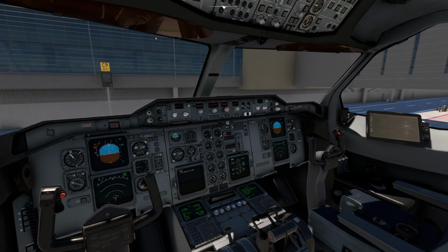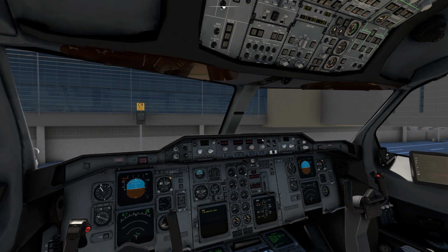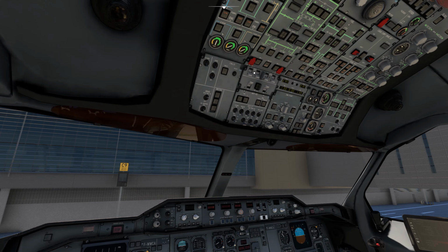And one more thing, I would just like to bring your notice to the FCU. This part of the plane is the FCU, which is the flight control unit. And over here, these two parts are known as the EFIS, or the Electronic Flight Instrument System. Right now you can see that the FCU is not on. FCU turns on when you turn on the pitch trim. So it's a sequence. You get the IRS alignment, you can turn on the pitch trim. You turn on the pitch trim, you can interact with the FCU. So now as soon as I turn on the pitch trim, you can see.